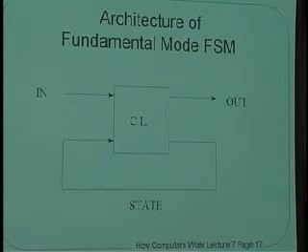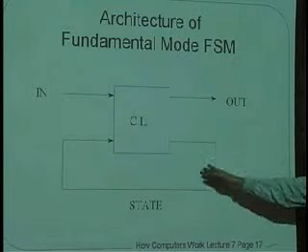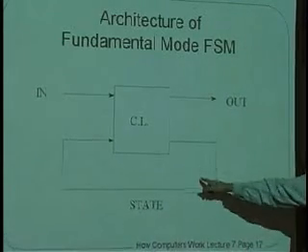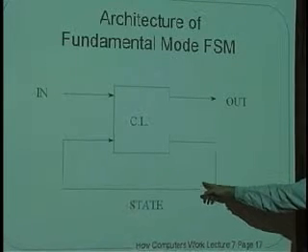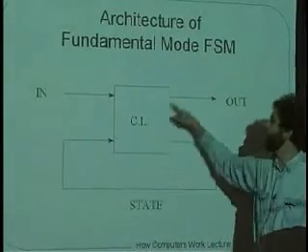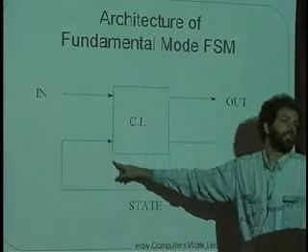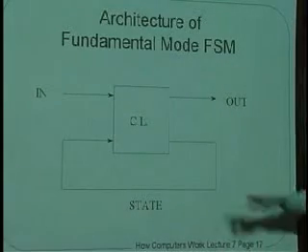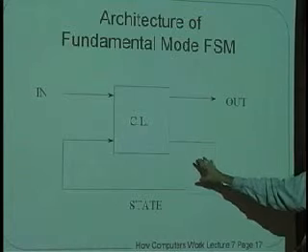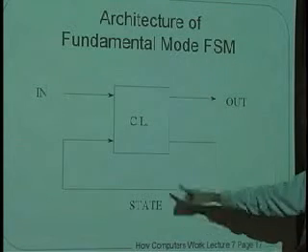And in general, the architecture is exactly that architecture that I showed you in the last class. And if you remember, that architecture was a disaster. We tried to have students at the blackboard, right? Adding numbers around and around with no delay inside of here. But what I'm opening up the magic box now here is saying that ultimately we build circuits that look like this. And what was the circuit that we just built? We used a selector here, and we had the output and the feedback be the same signal going back around like this. And we had no synchronizing element in the loop because we're trying to build that element. And so ultimately we build it just out of some logic and wire for feedback.